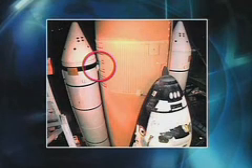At T+2 minutes, when it's time to separate the boosters from the vehicle, there's a large bolt in that attach point that fractures after a pyrotechnic event and allows the vehicle to move away. The forward portion of that bolt is captured within the bolt catcher, and the bottom portion of that bolt is dropped into the thrust post. Next slide, please. Here's a close-up view of the bolt catcher.